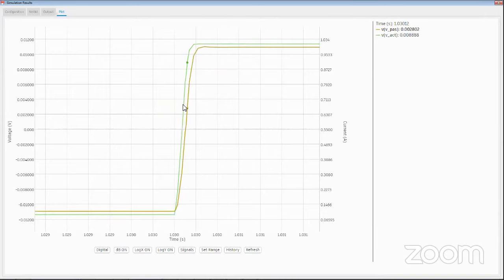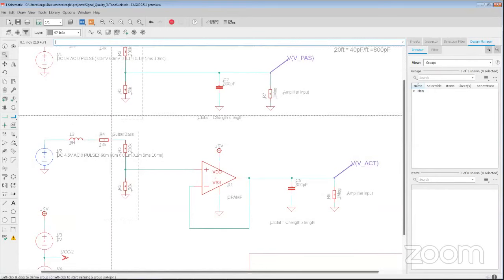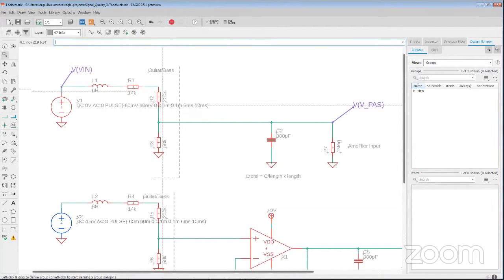Now, I've done something to make the passive look good here. What I've done is I've set up its potentiometer to have a relatively low volume. So right now on this 250K, what's visible to the rest of the circuit is really about 50K, because you take all of these impedances at the various frequencies, and really what ends up dominating is this resistance here. But what happens if we now have max volume, which is what many of us may do?